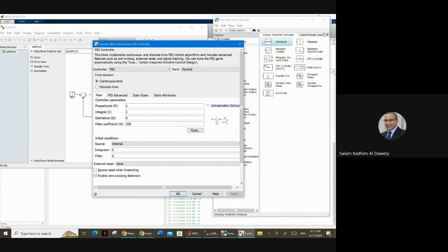So here the value is what they call the reset. So it is 1 upon the real I. If I put integral action equal 2, it means the real I is 0.5, so it should be shorter. The value is the inverse. So now you can see that by increasing the I here, it means faster to reach. The reality is the inverse. So here I is the inverse of the real integral action. This is the reset. Now we apply.